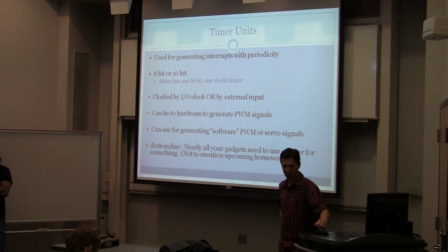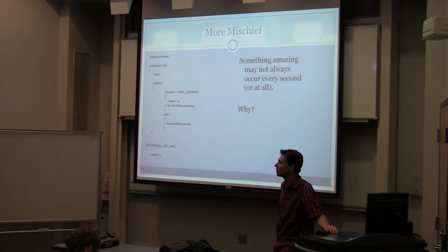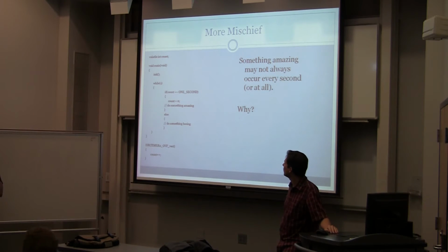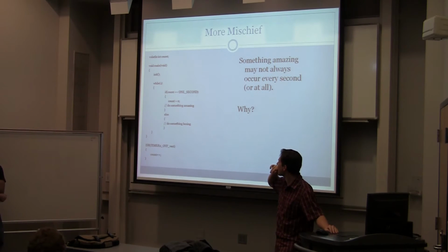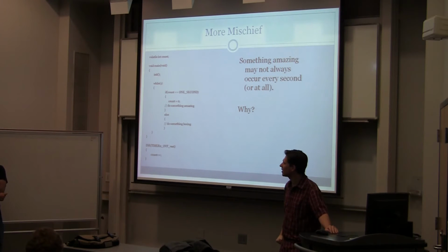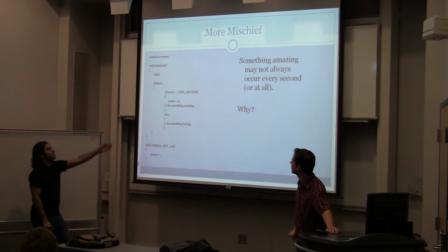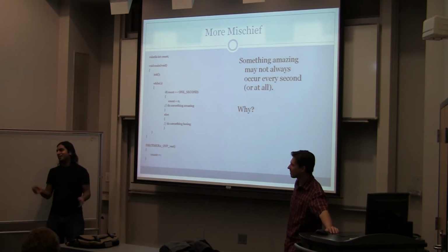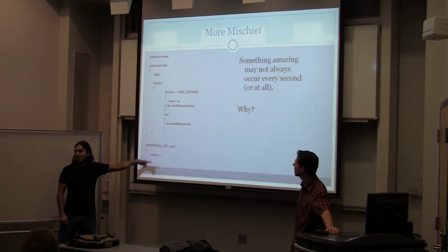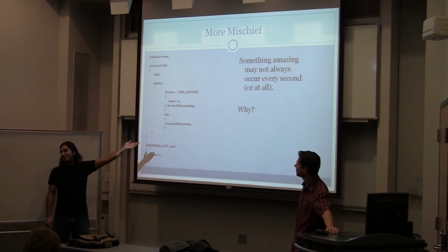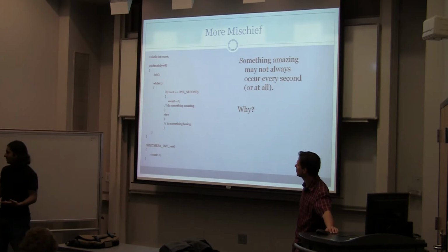Yeah, in the previous thing, if it was something like 2 milliseconds instead, how would you handle it? If your timer was counting at like 1 millisecond, instead of 1 second, if it was like 2 milliseconds. I mean, everything should work pretty much the same. Right, so basically, 1 second would just be some number, like 1,000, because this is counting up at every millisecond. So in this case, it would change from 1,000 to 2. Right. But the rest of the code should be pretty much the same.